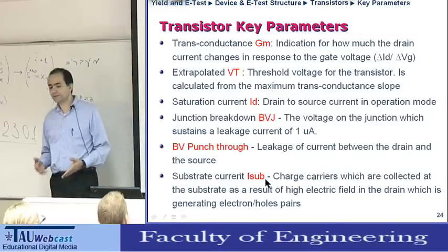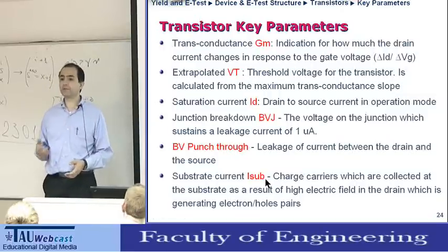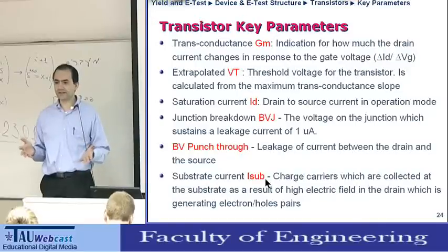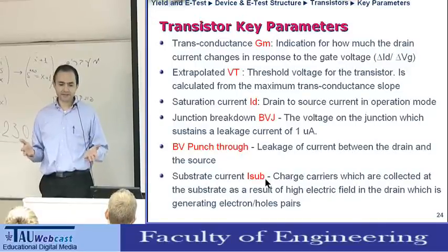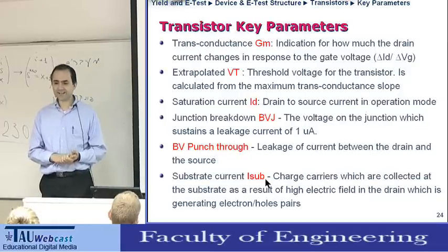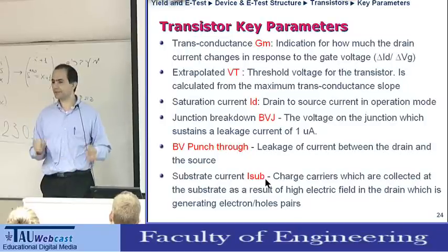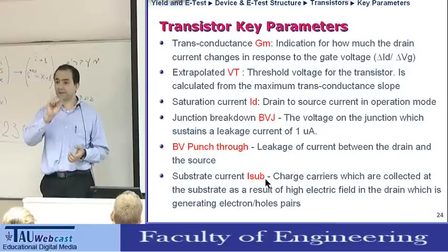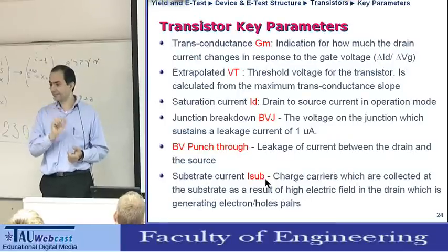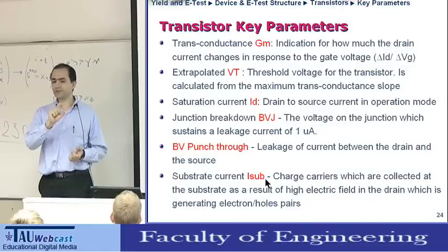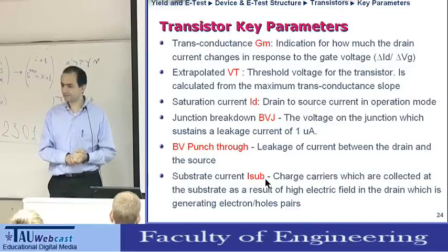And nowadays, we also measure the leakage current through the gate. I know that you were taught that in a MOS transistor, the gate is not leaking. But that's in the old textbook. In reality, these days, the gate is leaking as much as the leakage between the source and the drain. And the reason is that the gate is so thin that it becomes leaky. It's no more the thick gate oxide which is used for all the textbooks. Okay.